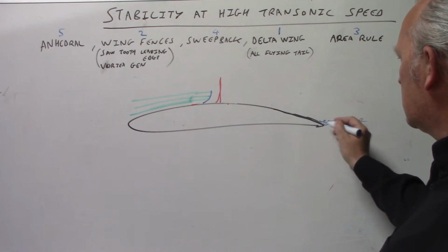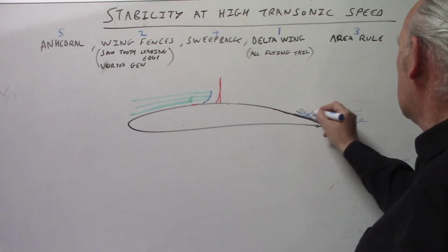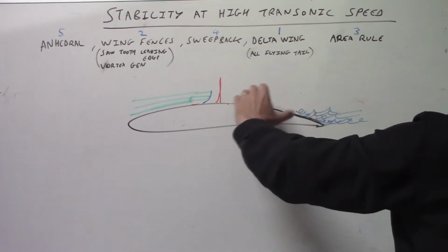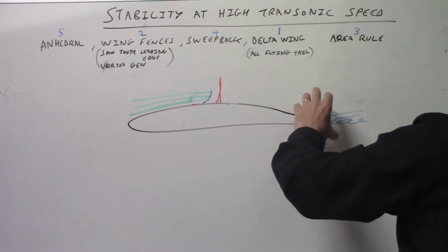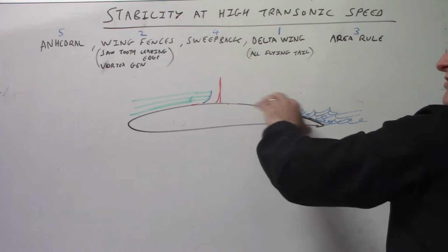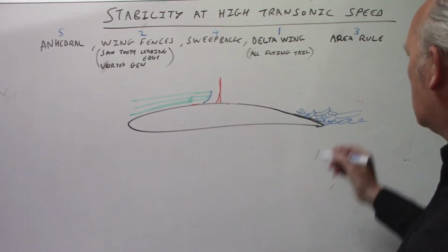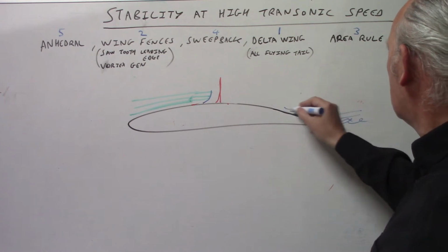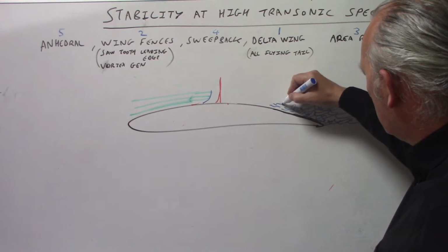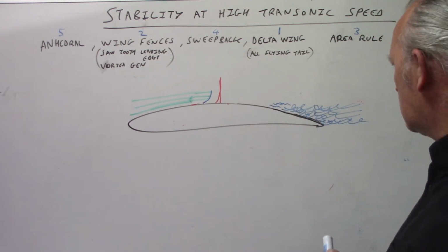You'll start to get a little bit of turbulent flow, and as you go faster, more and more of the air, which you're asking to change direction, wants to go straight on or remain stuck to the wing. The faster you go, the harder it is for the air to stick to the wing. So it gets ripped away and becomes turbulent. Here you'll have a little bit of transitional flow where it starts to wave a little. It's laminar along here, then transitional, then turbulent.